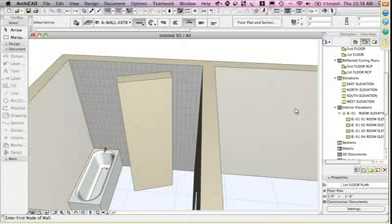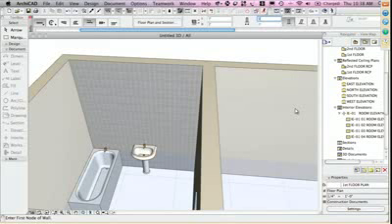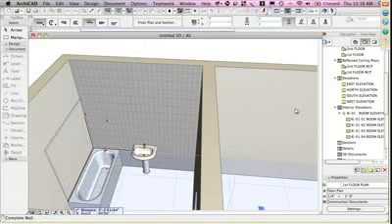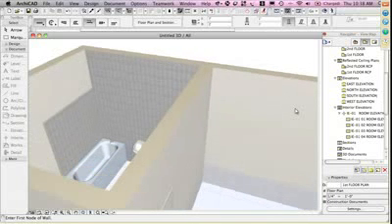Let me just undo those last two that I picked, and let me make it just go from, I don't know, maybe it's 2 feet, actually going up to 7 feet, and it starts at 2 feet. And I'll make it a very thin wall. Could be as thin as you want. I'll make it 1 inch just so it's not really paper thin, although tiles probably wouldn't be anywhere near that thick. And I'll just click on this point here and go to the end. And you see I've just created a piece of tile applied there.